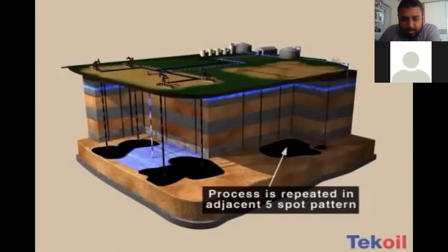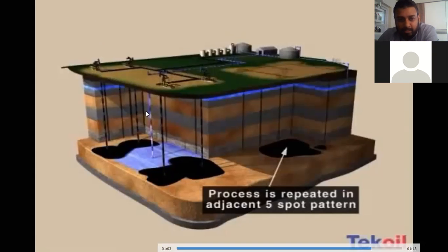Sir, sorry, I have another question. Let's say the pressure of the reservoir is equal to the pressure at the surface. Then besides the jet pump, how do the engineers handle the situation? Then they have to inject water, as you see, or they can inject gas also, if gas is available nearby and they can source it. Sometimes they take nitrogen from the air. Sometimes they take CO2 and inject it back into the reservoir, which creates pressure or a piston-like movement for the oil to flow out to the surface.